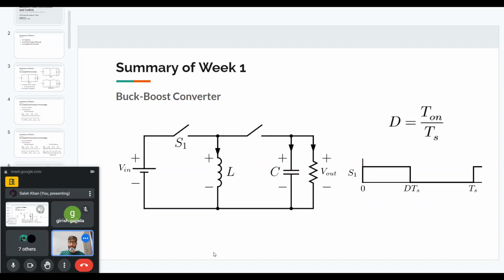Okay, so let's take an example of the buck boost converter, because here we will be able to take both of these equations. I want to find out what is the expression of the output voltage in terms of the duty ratio, D, and the input voltage. Before that, I will label my diagram. I have a diagram with, again, the input voltage, output, resistive load or some other load, a capacitor C, L, and two switches.